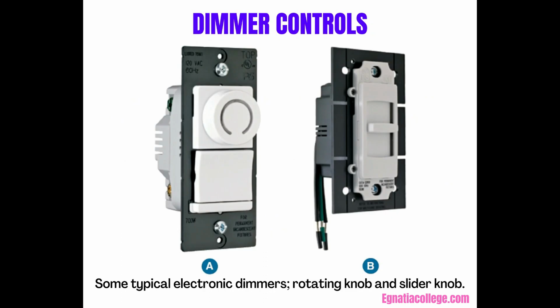Dimmer controls. According to their Canadian Standards Association (CSA) listing, solid-state electronic dimmers of the type sold for home use are intended only for the control of permanently installed incandescent fixtures. For residential installations, the dimmer commonly used is a 600-watt unit that fits into a standard single-gang wall box. Both single-pole and three-way dimmers are available.